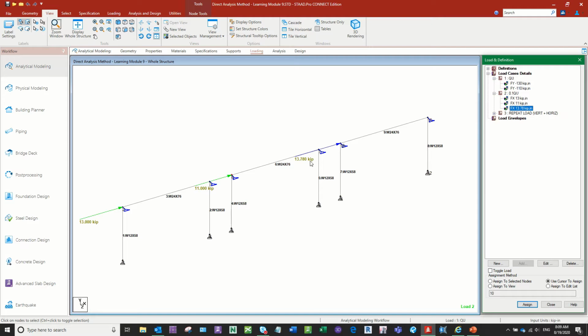which is 0.3%. Now the notional load can be increased to account for imperfections by 0.2% of the vertical if you don't model the imperfection. If you model the column as straight and nominal, as we would normally do in our analysis, certainly as we would draw it on our drawings, we would have everything shown as perfectly plumb and square to one another.